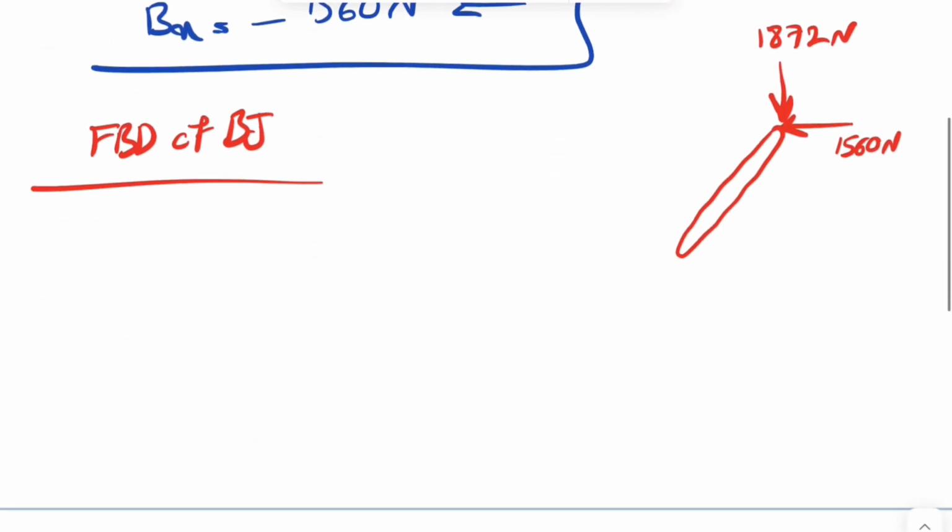And for the forces that we have at point J, we can consider one force F, one force V perpendicular to that one, and a moment. And that's going to consist of all the internal forces and bending moment that we have at point J. So as we discussed in the previous questions, we're going to define different x and y for here.